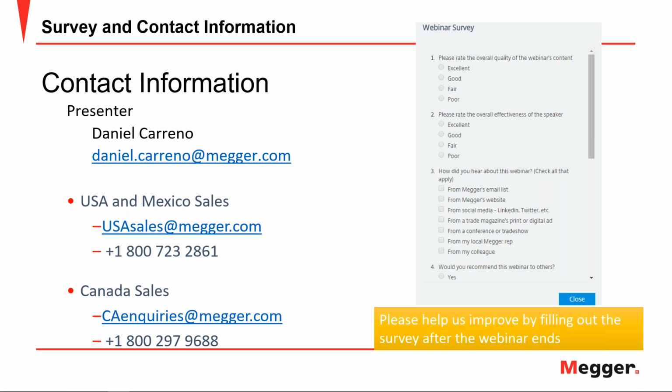As per IEEE, any breaker with a voltage rating of 1000 volts or less is considered a low voltage circuit breaker. So it's quite an industry practice that people would use primary injection testing for any circuit breaker rated less than 1000 volts.